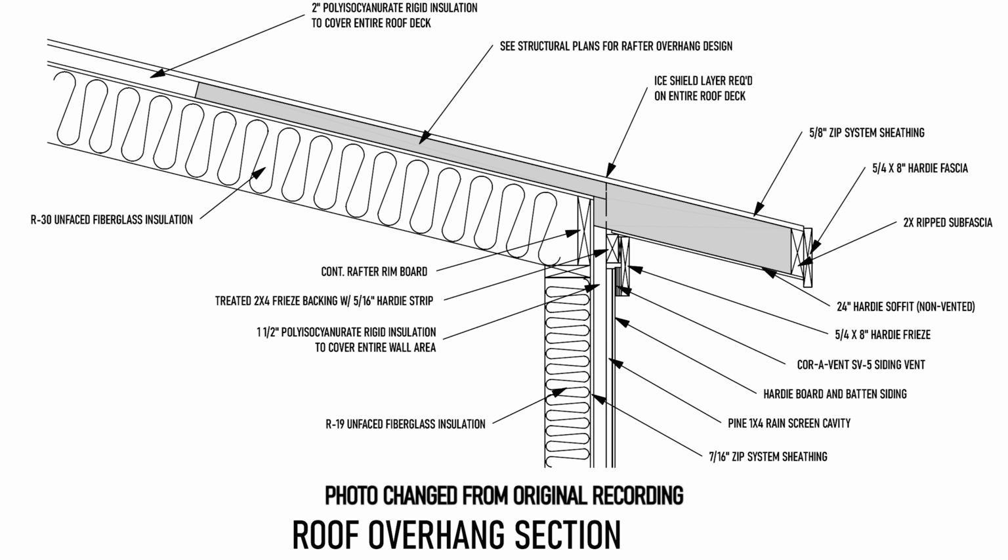This is just a particular example. This is a fairly complicated wall assembly. They have some rigid insulation boards on the outside of their wall assembly. So it's kind of complicated, but this is the basic idea. You're going to see usually this first layer on the inside. There's your 1/2 inch of drywall. And then you're going to see this squiggly looking stuff. That's your stud bay. That is where the insulation exists. And then outside that is your sheathing board, that wood sheathing of some kind that's going to go outside on the studs. And these two big thick layers, those are going to be, in this case, some rigid insulation.